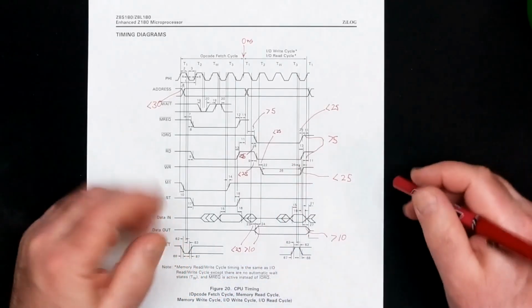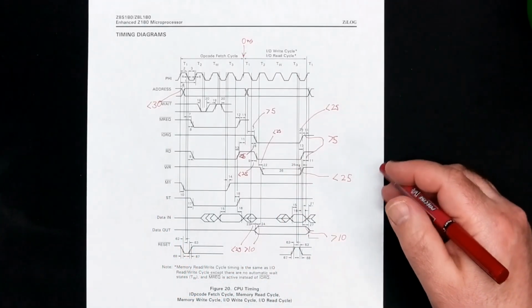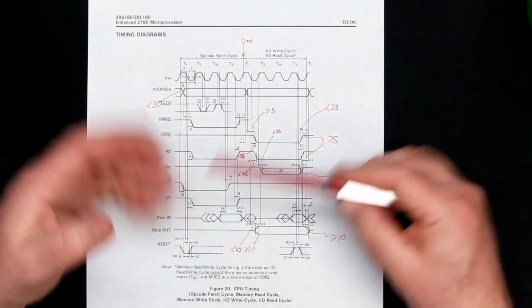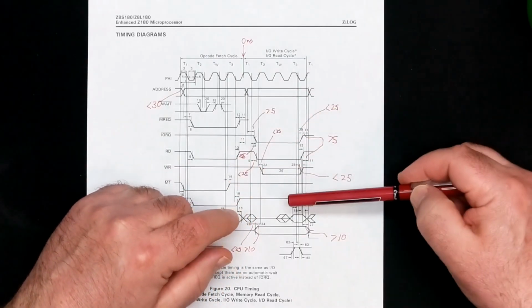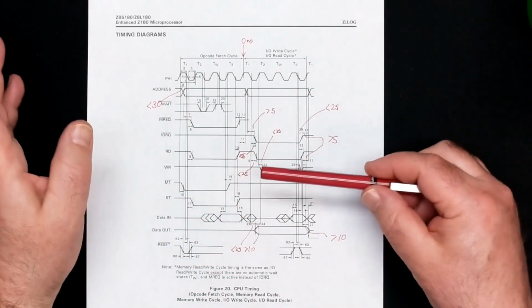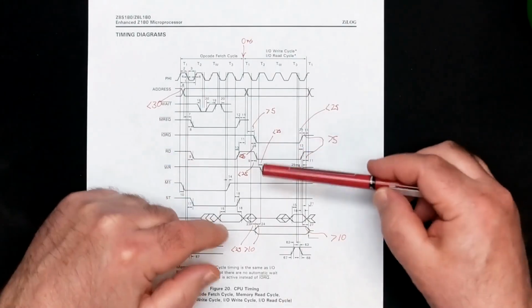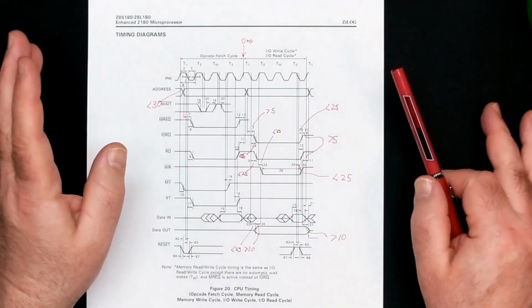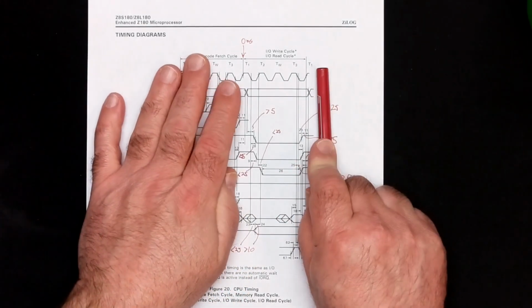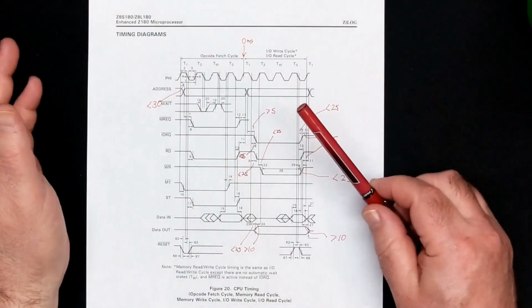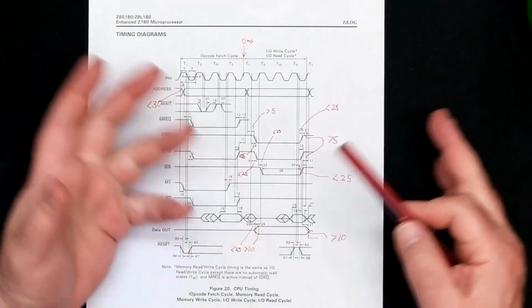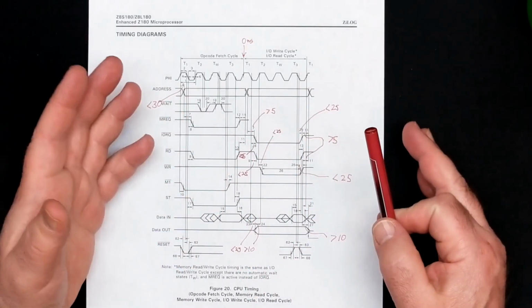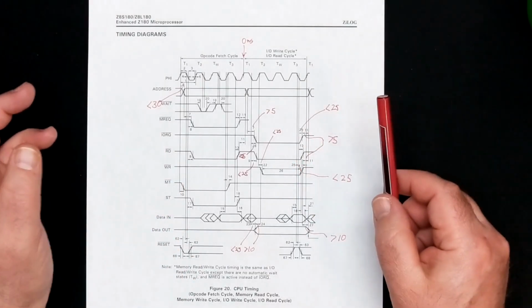Step number 1, get a diagram that's representative of the problem you're actually trying to solve. Today, all I want to do is recreate this timing diagram in a Verilog test bench so that I can connect it to modules that I'm designing. I don't care about the modules today. That's not relevant at all. It's just, how do we take this timing diagram and express it in Verilog in a way that's readable, understandable, and if I make adjustments to it, the whole thing doesn't fall apart and everything starts moving around in weird ways.